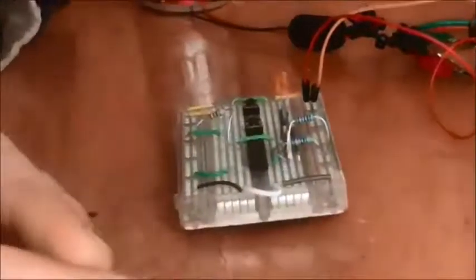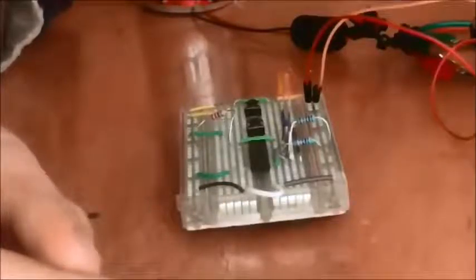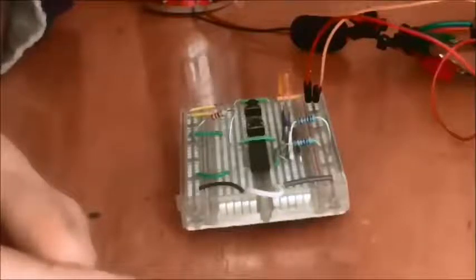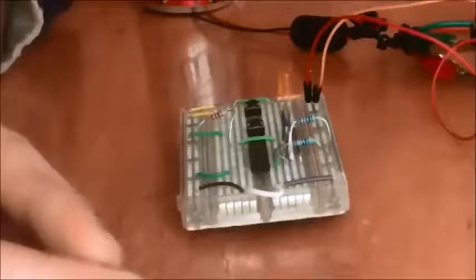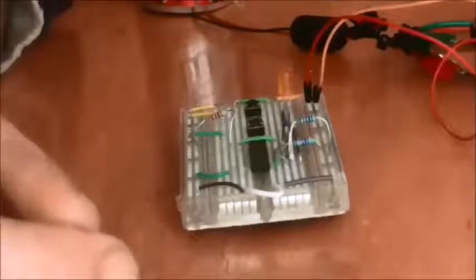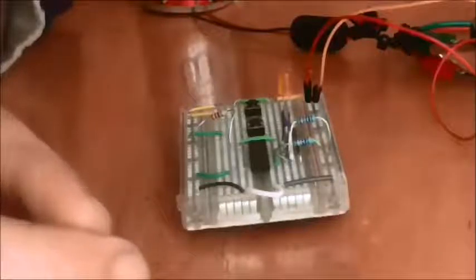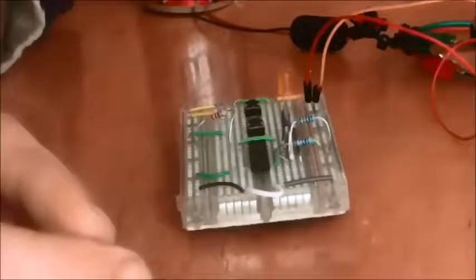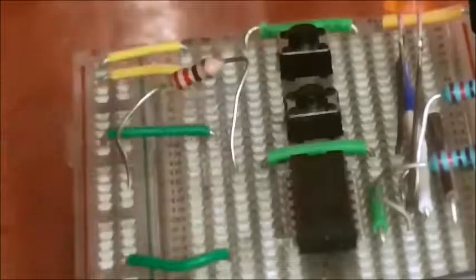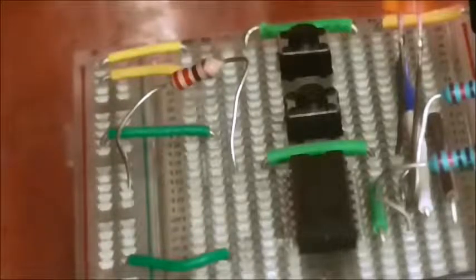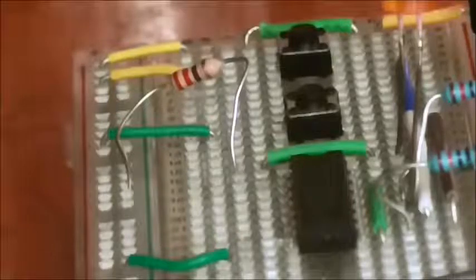Well, just as diode logic gave way to transistor to transistor logic, transistor to transistor logic is now giving way to a technology called CMOS. And CMOS is complementary metal oxide semiconductor, and basically what you get is a load of field effect transistors packaged together to make the logic gates, and they're all done in this little black chip here, and that is a quad NAND gate. It's a 74HC00N.